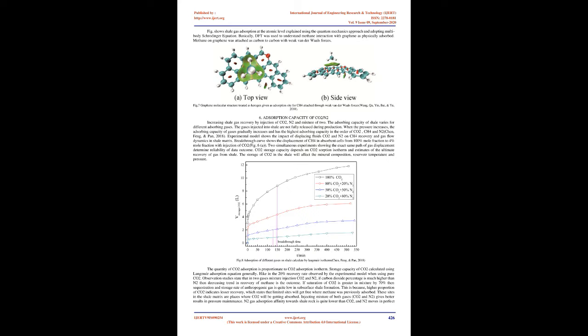The outlet valve in the model is opened simultaneously to collect released methane gas from the rock sample. Flow rate for injection is kept at 10 ml per minute and the adsorption column at 10 MPa. The CO2/N2 is injected in the adsorption chamber as liquid to displace the methane gas by its greater affinity towards shale rock.